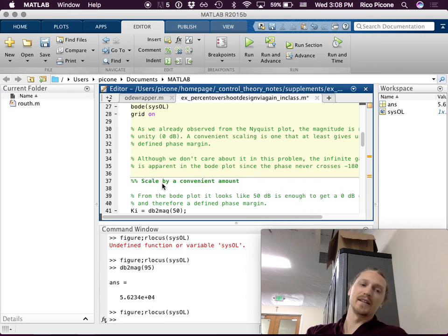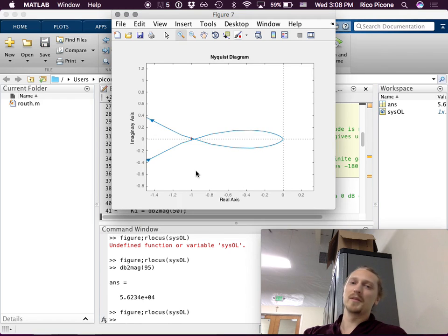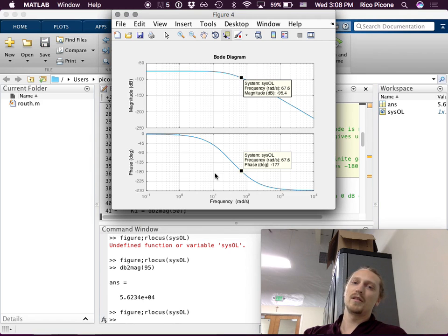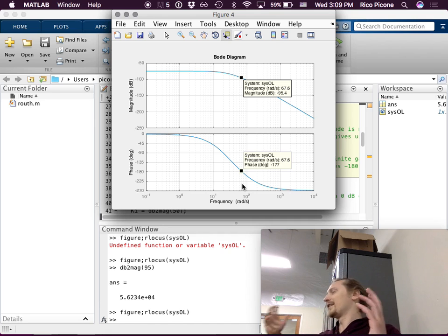It would be an accident, because we're shooting for a positive gain margin or a positive phase margin, right? If we ended up with a negative phase margin, then we would have made a mistake at some point. One of the easiest ways to make a mistake here is to forget that you have to measure from negative 180 up for the phase margin. If you went down for the phase margin, you would already be unstable, and you would have to recognize that.